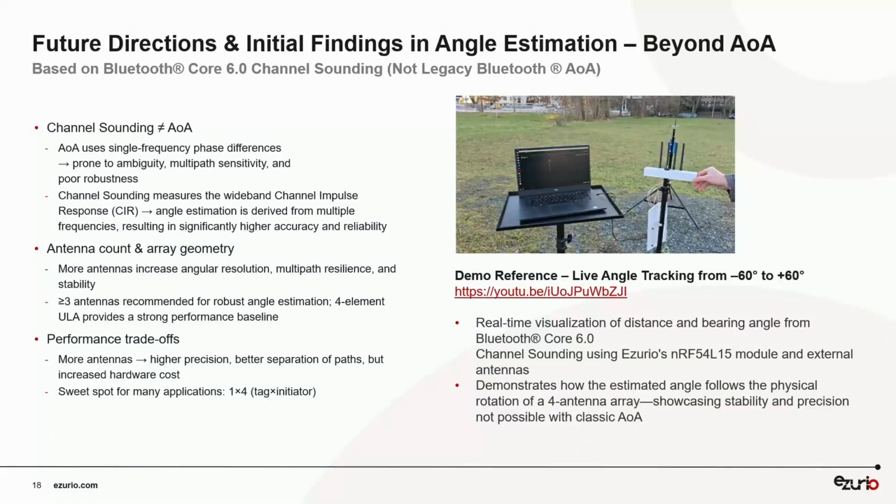Now, the way to do that effectively that we found is more antennas or adding some elements of sensor fusion to your system to be able to interpret that data a little bit better. Ultimately, we found 4 antennas is kind of the sweet spot of a realistic implementation scenario. You can keep doubling and doubling, but who's going to put 8, 12, 16, 20 antennas in a system? You're back to the complex antenna arrays that limited some of the real growth of RSSI-based systems.